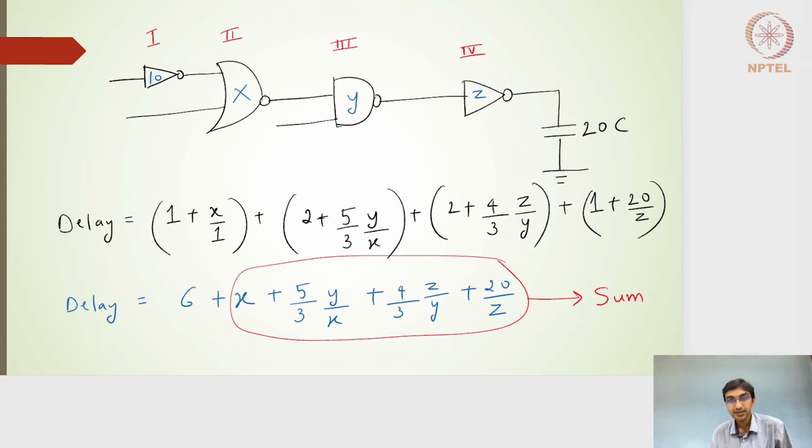so I have this particular critical path circuit, and then the delay of this is written here. So this is the parasitic of the first stage, and then the G value is nothing but 1, multiplied by H value, which is X by 10. Right, so it will be X by 10.